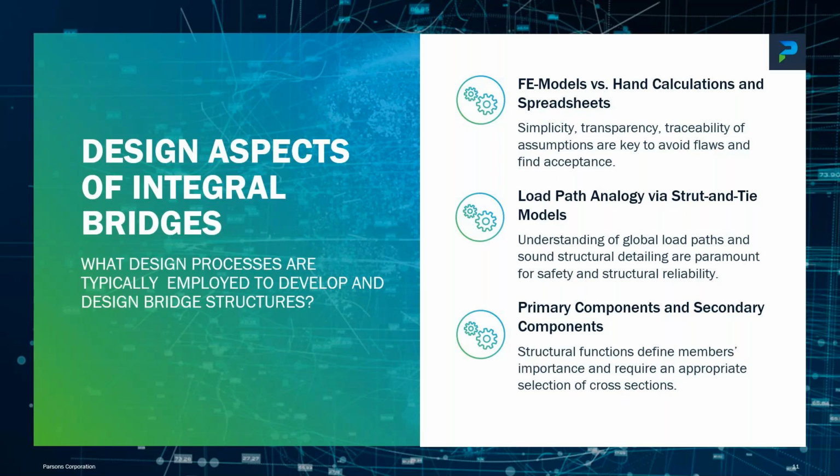And this is often ignored, because the assumptions that you make as an engineer, you need to verify them later when your design is there. Otherwise, you may introduce flaws and not find them. So the power of hand calculation is this: you know already what to expect when you get your structure into the computer, and you have a very good way of validating computer results. If you don't know what the computer will produce, you are basically relying on the computer results, and this can be very, very dangerous. I'm not saying that the program is doing the wrong thing, but you may have put the wrong values in, or you have made the wrong assumptions. And this is the power of spreadsheets and hand calculations. Do both.